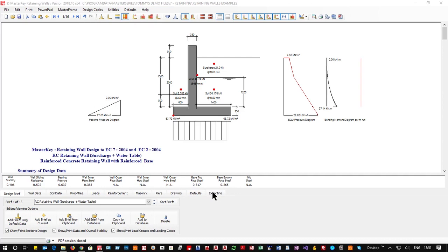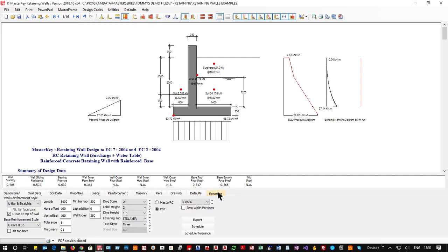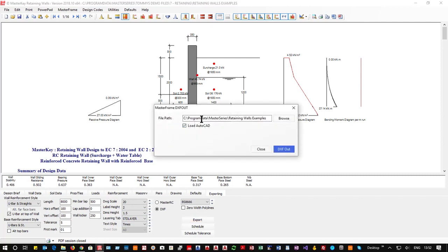One thing we haven't looked at yet is the exporting. And we are able to take a snapshot of this. Okay, it's nice and chunky. Probably get away with 250 walls in places. I can say this wall is going to be 50 meters long, but we'll do it in 8-meter lengths. We will accept these basic defaults, and we'll have minimum 500 mil gaps, and we'll go to 8666, and we'll export this out. And out it goes, and it's going to put it into that example.